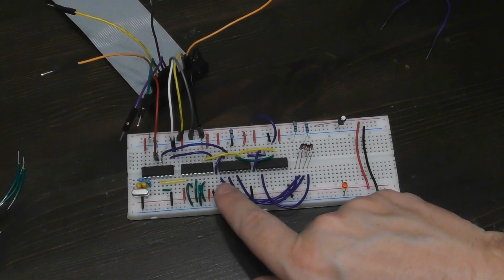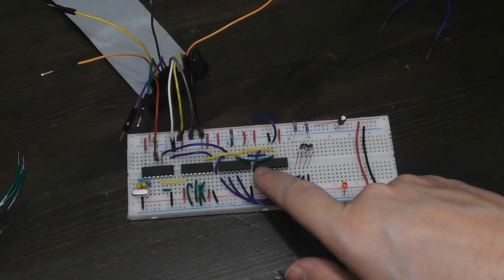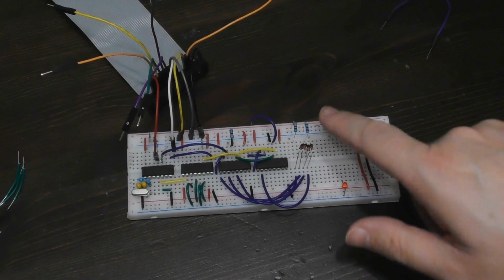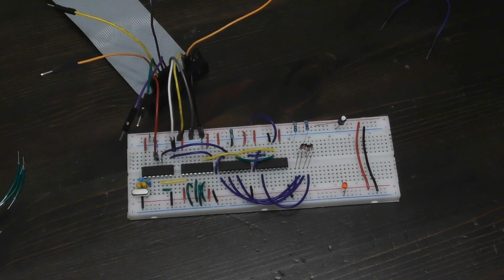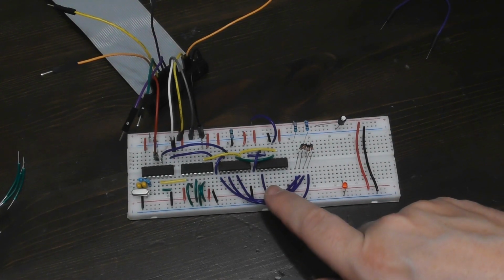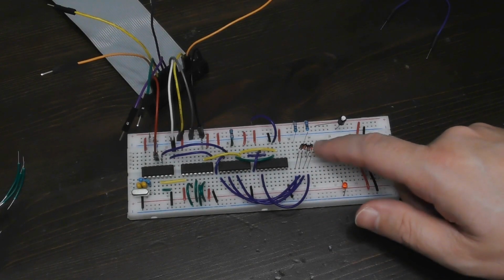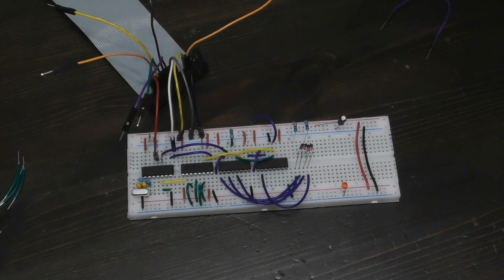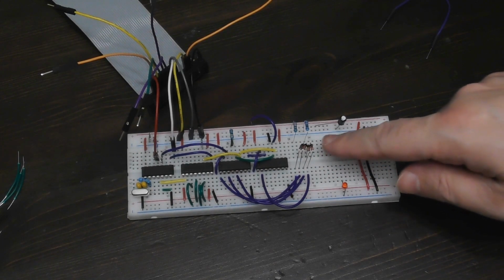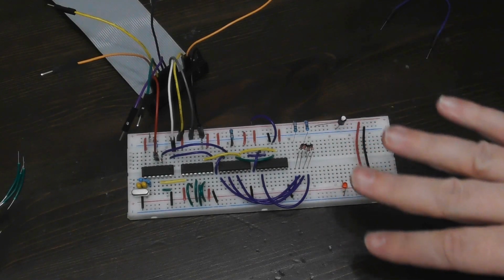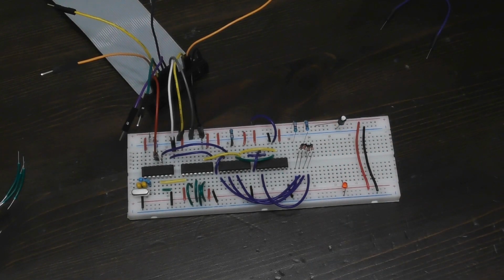So there we go, we have clock bits 0, 1 and 2 and data bit 5 going through the diodes into this pull down resistor, so that if any of those is high, then the signal at the junction here will get pulled high. And really what I want to do next is just look at that on an oscilloscope, because the key thing here is making sure that that is happening at the right time during the revolution of the disc. So let's get the scope hooked up again to that.